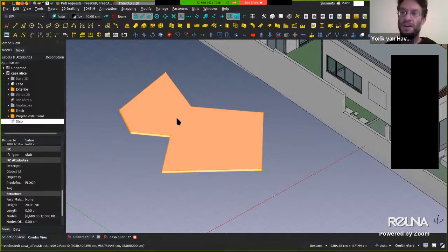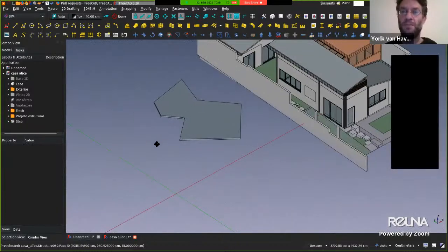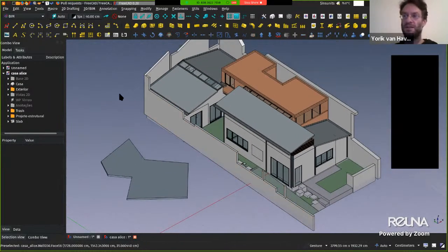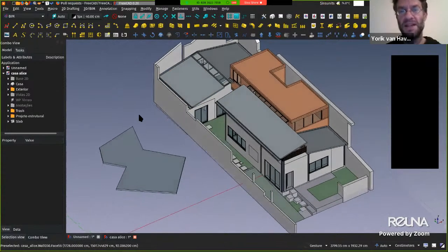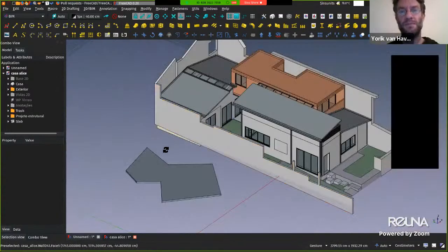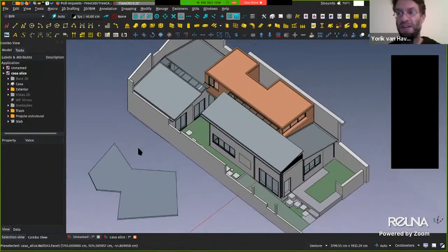And this is something tremendously precious in FreeCAD, that you're not forced to use BIM paradigms to build a BIM model. Basically, you can model BIM stuff in FreeCAD with any other tools from other workbenches, or even with other software, and you just import the geometry from another software, use that in FreeCAD, and turn it into a BIM model.